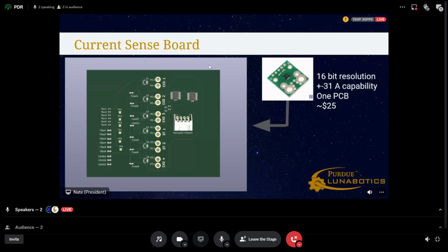And you can see the connector there in white. That'll be where the TNC connects through I2C to communicate the data from both ADCs, and they'll be individually addressed, so software can pull data from either one.